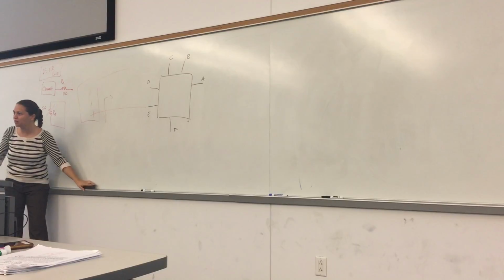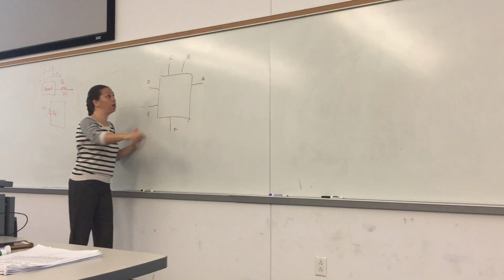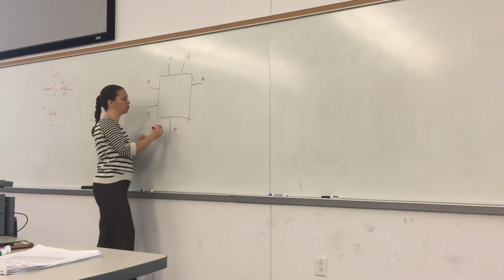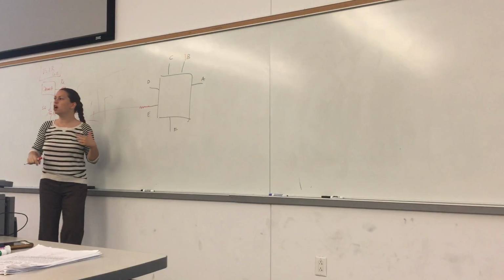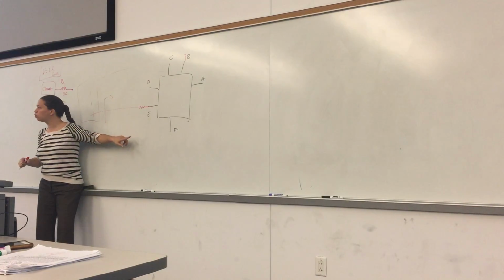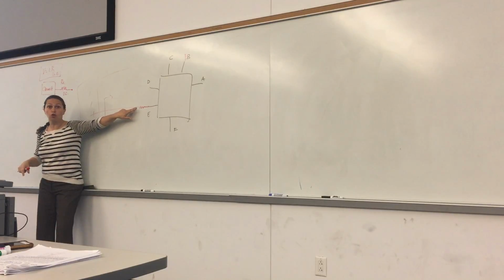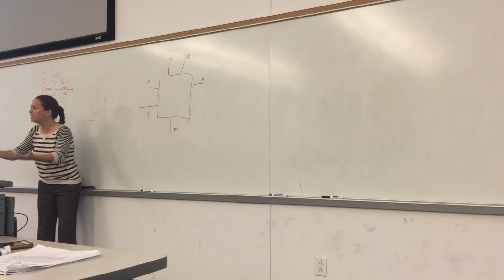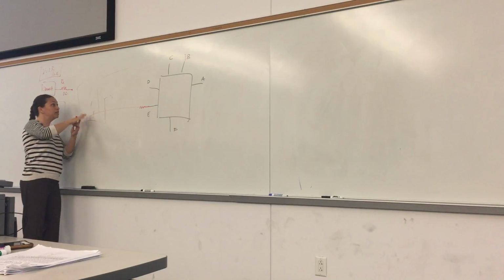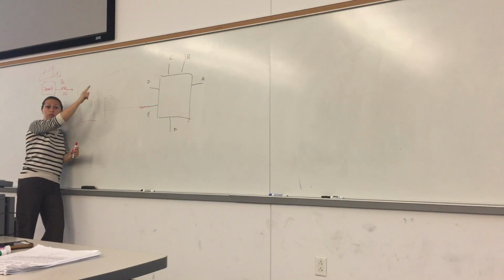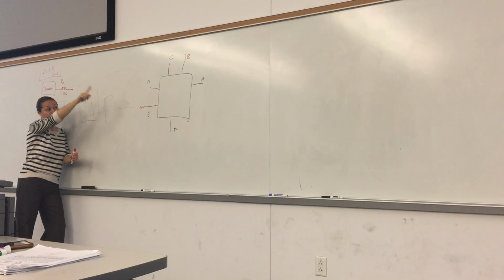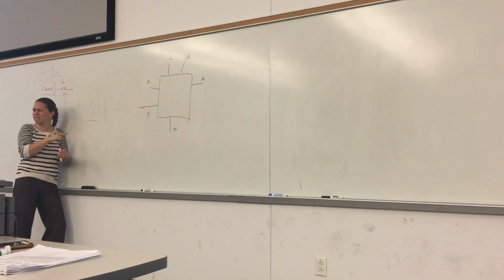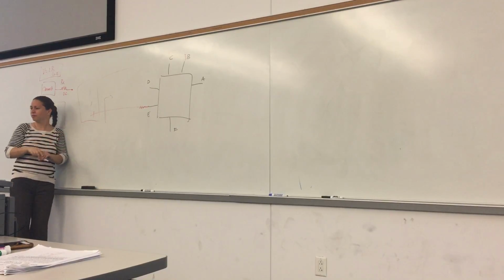That's an important detail because, as in that problem, you have resistors here, floating resistors. Now, if you are looking at the circuit from those terminals, those nodes are connected to something. So you cannot really ignore those resistors. They are not floating. Because the assumption with a resistance seen by something is that something is looking at that circuit in between the terminals B and E. Does it make sense?